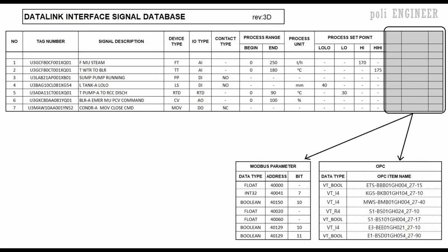Next, we will have a look at software I/O database. This refers to signals using communication protocols like Modbus, Profibus, OPC, etc. This is a very vast topic, and here I will include only an overview. Usually this communication method is preferred when we have a large number of signals but want to cut short the cabling cost for each individual signal. As these are communication signals, in my opinion, these are not so reliable too.